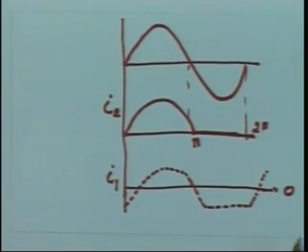I do not know how many of you have seen the waveform on the oscilloscope. If I keep a waveform which has a DC bias in AC mode, how does it look? The DC bias goes. I get a waveform symmetrical along the x-axis. If I keep it in DC mode, automatically I get the DC bias. You go back and check. You give a sinusoid using a signal generator, give a DC bias, keep it in AC mode.